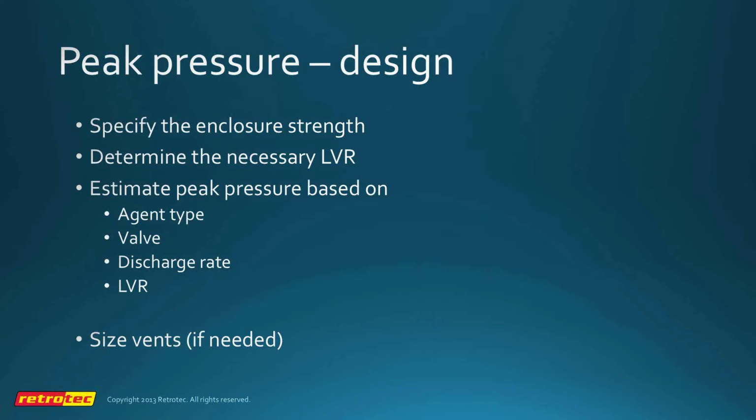They always put in a vent for ISO, or usually the European model. For the American model, the NFPA testing goes on in North America. They generally install a vent if they determine that the peak pressure in the enclosure is going to be excessive. So there's a very big difference in philosophy.